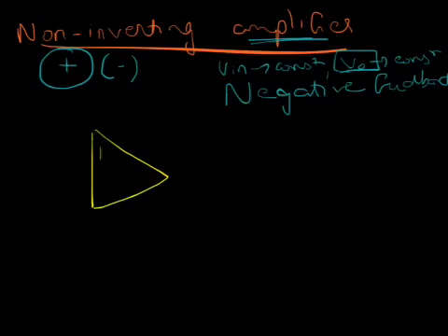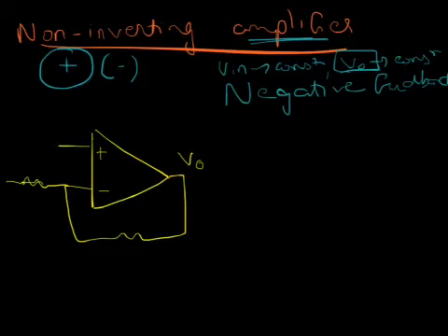So we have our op amp. Like before, we are going to put a resistor to the negative terminal for establishing negative feedback. Before, we had another resistor here. We had given Vin here and we had grounded this. But now since we want the opposite signs, we will ground this and we will give Vin here. Again, let's name these resistors. Let's call them R1 and R2.